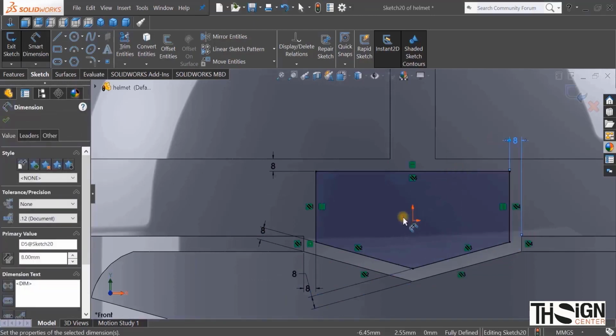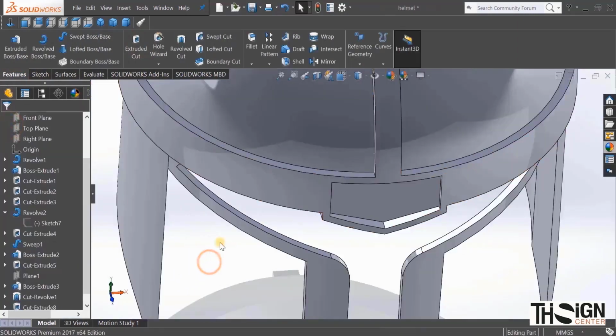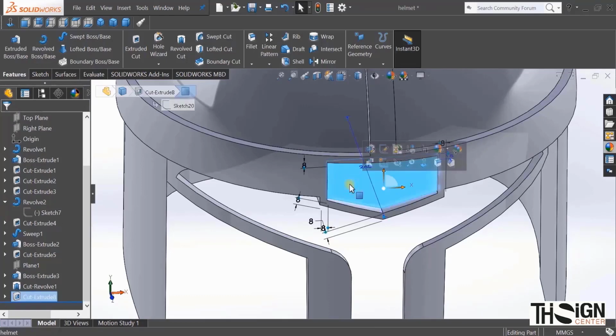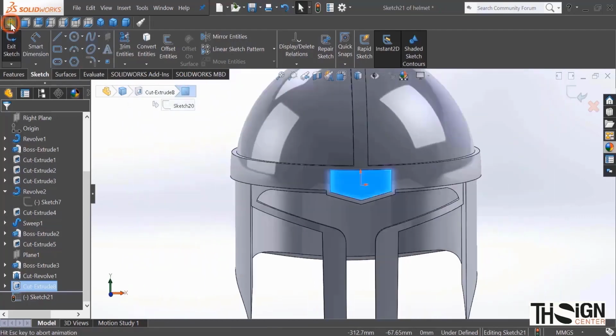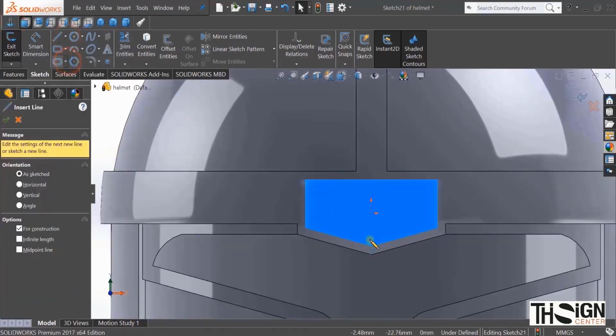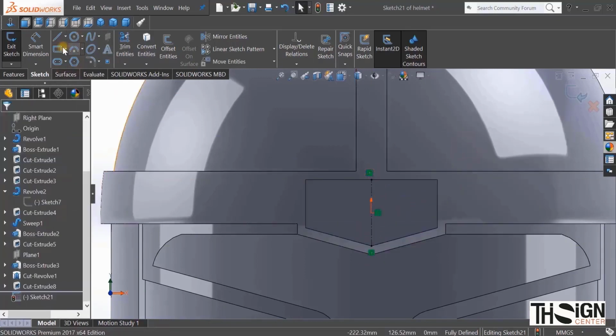After you set all the distance between the line and its edges to 8, then go to Extrude cut. I'll sketch the letter M on this face, select the face, then click sketch. I will put the center line first so I can mirror after the half of the letter has been created.